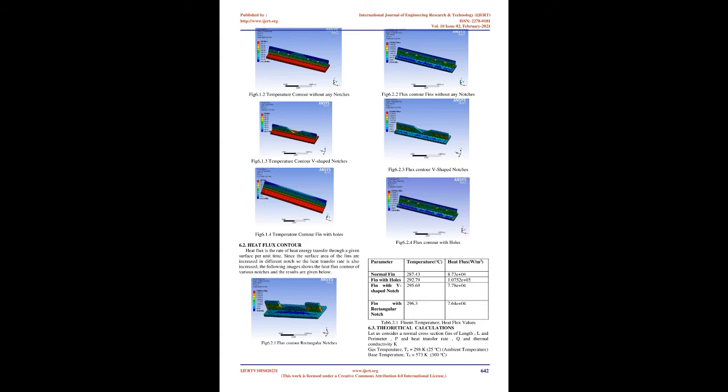After the mesh is generated, the boundary conditions are defined for the CFD domain, the mesh file is saved in .msh format, and the mesh file is imported into Fluent for analysis.